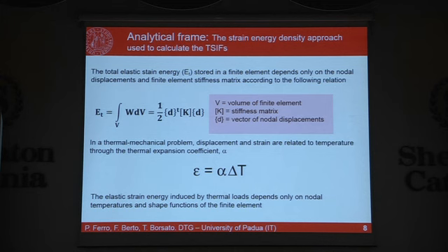And the temperature works like the displacement. I mean that also the temperatures at nodes are almost mesh independent. So one can calculate the strain energy density using a coarse mesh, not a very fine mesh, and then use the reverse formula, obtaining the value of the notch stress intensity factors. This is the methodology.